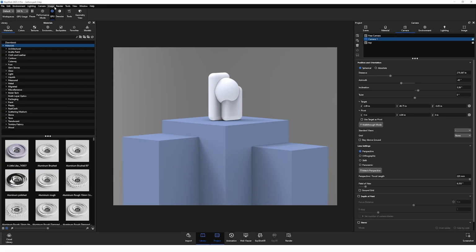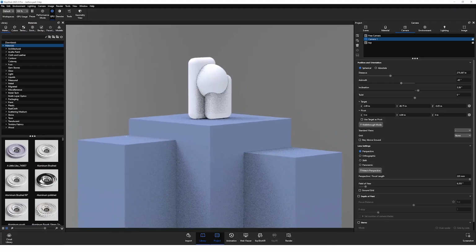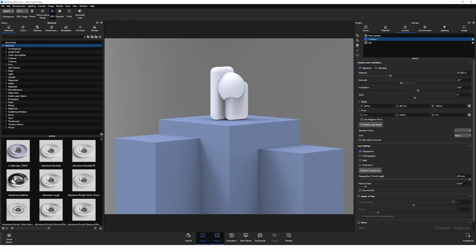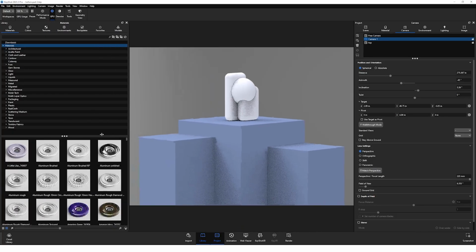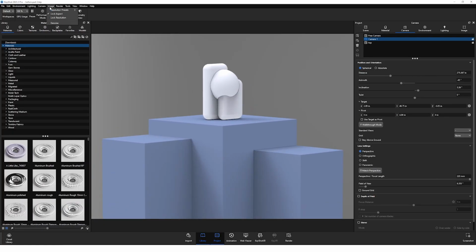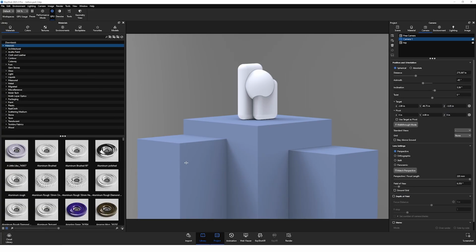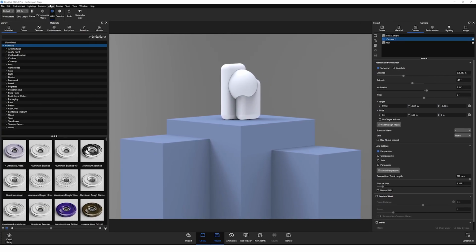And one last thing I want to do up here in the Image tab is uncheck Lock Resolution. This is going to give me the ability to maneuver this and position this window appropriately on our computer. And if you're ever not able to just move things around like this, it's because you have Lock Resolution checked. You can see with that selected, you're not going to be able to do as much. Once you hit the boundary over here, you're not going to be able to squish this window. So I would always recommend this is unchecked and keep your lock aspect ratio checked though.